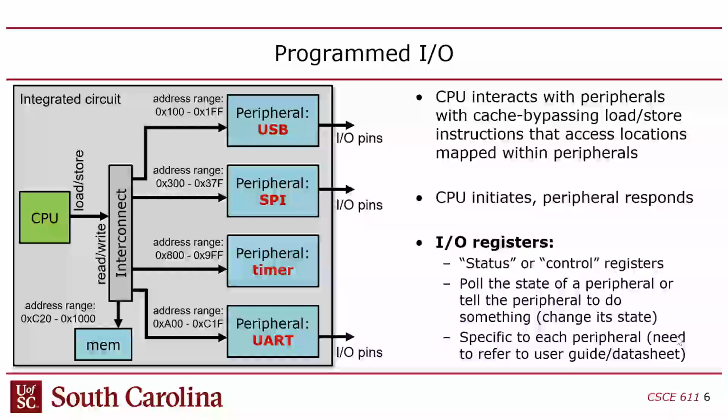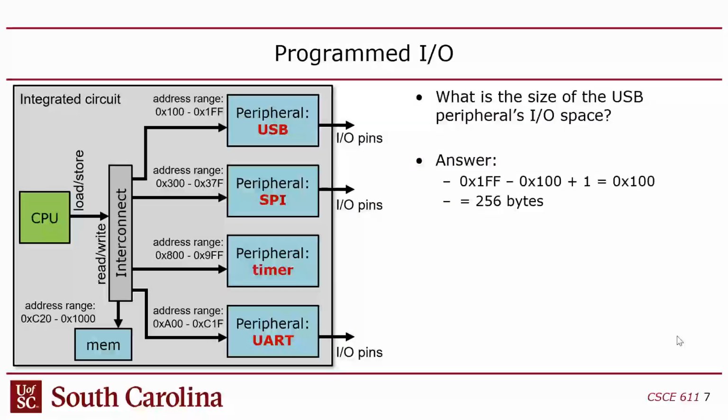Okay. So anyway, for example, you'll have a chip. Inside that chip, you'll have a CPU, and then there's some kind of an interconnect. This interconnect implements some kind of an on-chip interconnect between the CPU and the peripherals. This is usually a jealously guarded secret. For example, we have no idea how the interconnect works on an ESP32. They'll never tell you that. On the FPGAs that we use, we knew it was the Avalon bus or the AXI bus, right? But we don't know what the interconnect looks like.